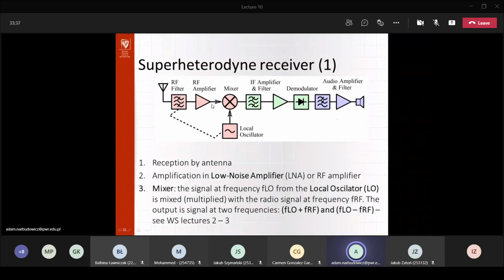Okay, so the role here is that we want to amplify the signal, but adding as little noise as possible, because we are still here in the analog domain, right? And analog domain, of course, in the sense that we are operating at the carrier frequency, at the non-digitalized signal, right? So we have to be really careful here with the noise.